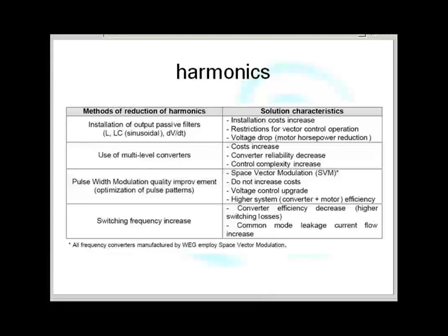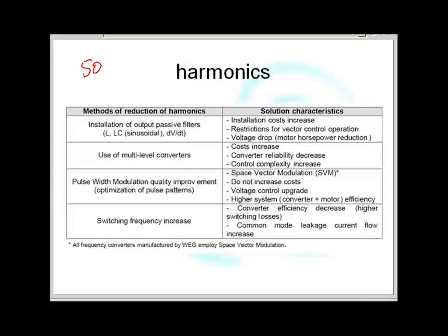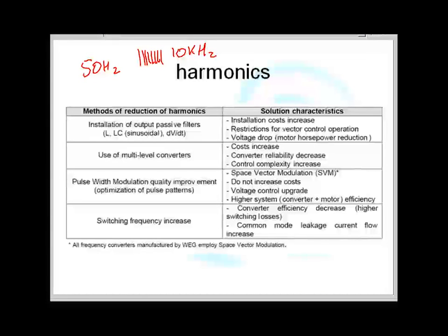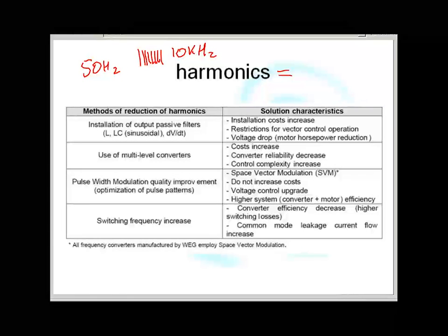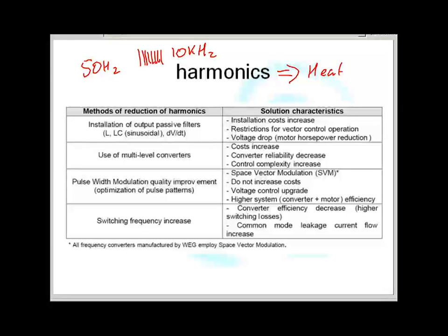The root cause of our problems is things called harmonics. VSDs produce harmonics like they're going out of fashion. The reason VSDs produce so many harmonics is because, in actual fact, the frequency isn't running around the 50 hertz mark. It's actually producing these radio frequencies at around 10 kilohertz. And those radio frequencies are going to produce lots of harmonics. Harmonics means heat. Harmonics means the damn thing tends to overheat the motor.